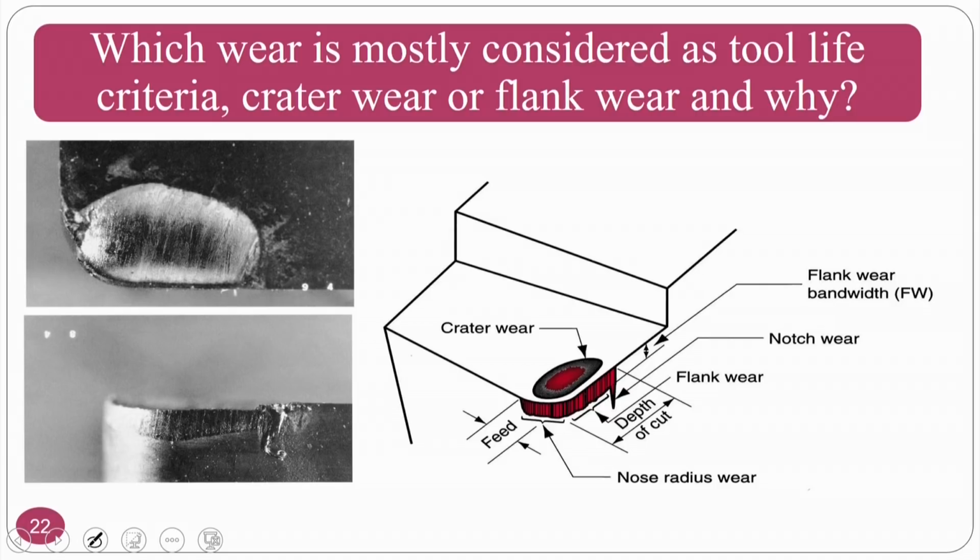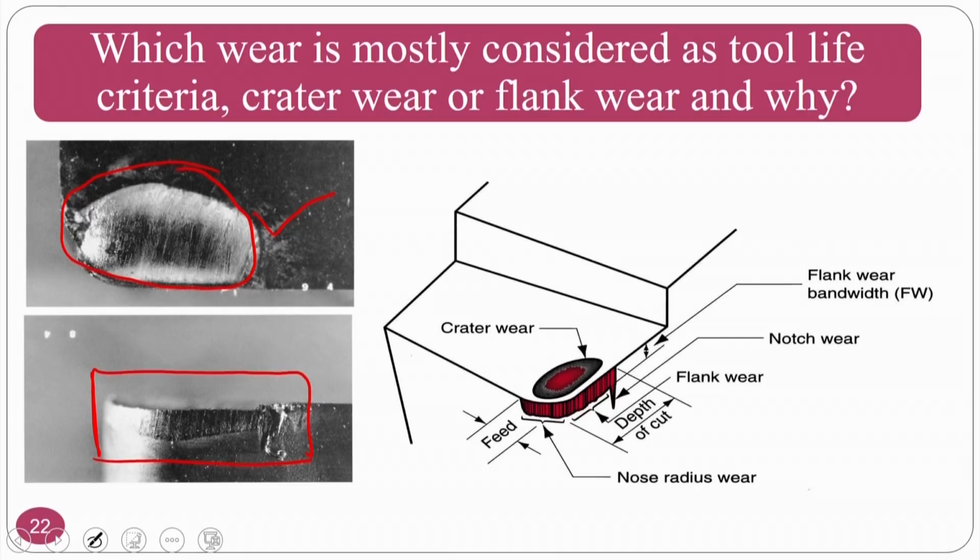Whenever the machining operation is taking place, crater wear takes place on the rake surface and the flank wear takes place on the flank surface, and the flank surface is the surface which will be in contact with my final product. So, whenever a customer asks me, I have to give a product to him in a good size, good tolerance, good surface finish and all those things. If my flank wear is high, in that circumstance I cannot give him a good product, because the product that comes out will not be in an acceptable form for a customer. Obviously, my chip will be in contact with the rake surface, which causes the crater wear.